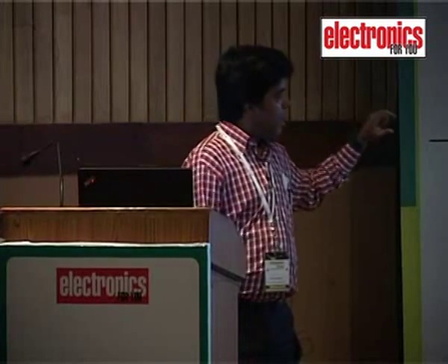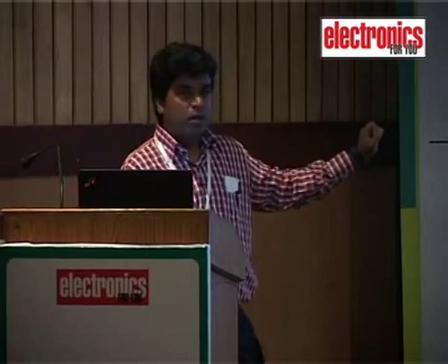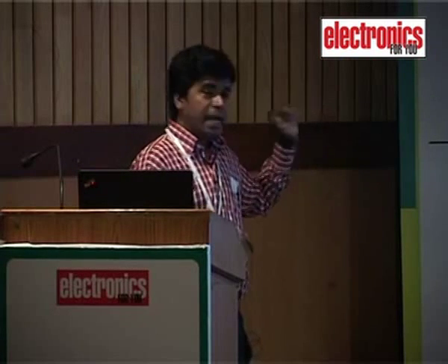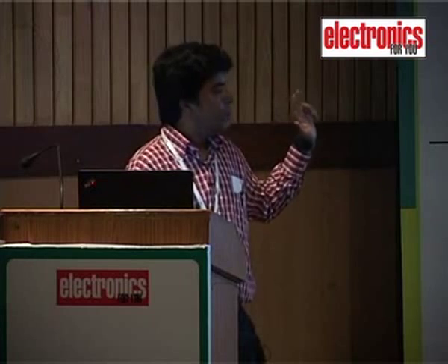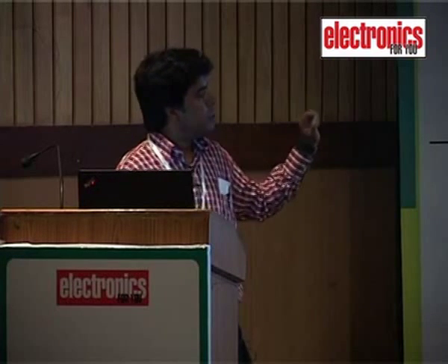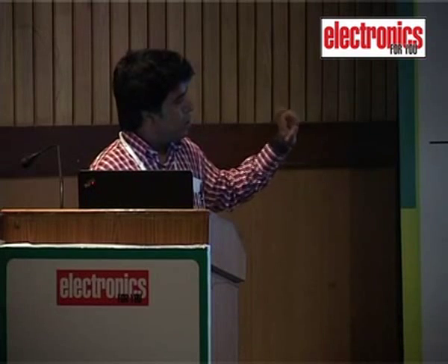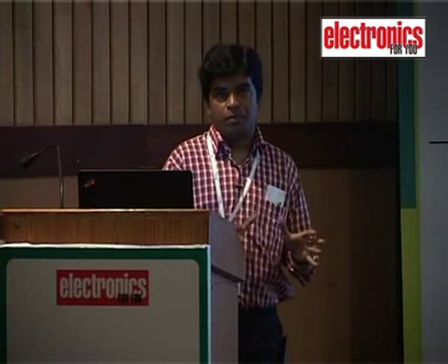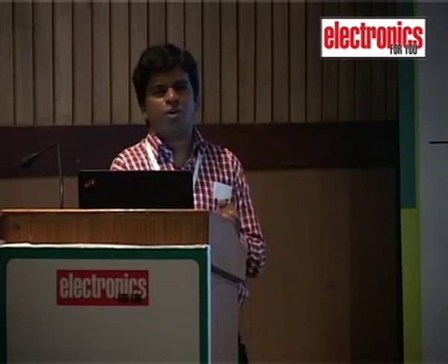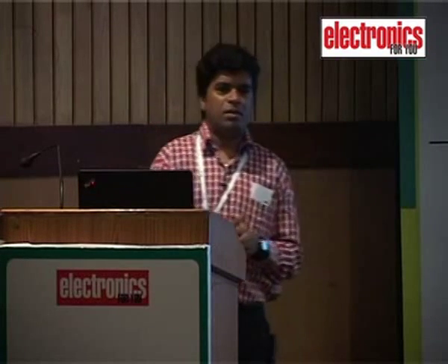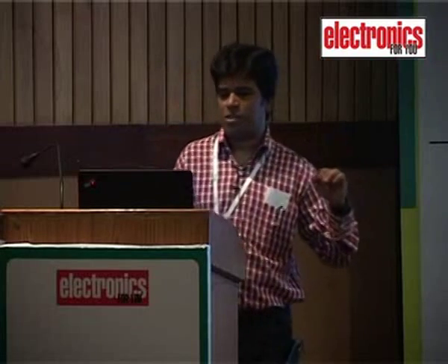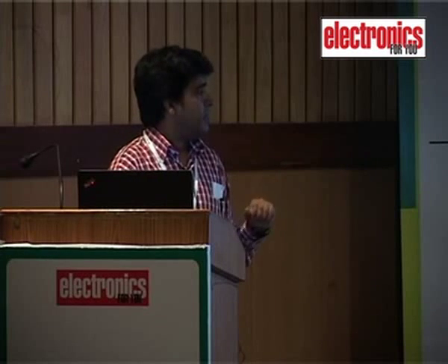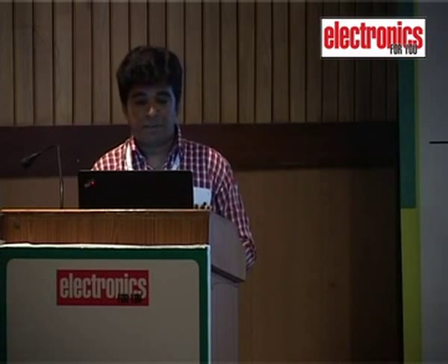Similarly for green, and for blue we are ORing 3 pixels out of the available 8 of blue. So what we have essentially is B0 and B1, G0 and G1, and R0 and R1. These are redundant bits which we can ignore. Their intensity is going to be very low, so even if we ignore them, it is not going to make much difference in the final pixel. This is one level where we have good compression. The unused bits are redundant, and that's how in 8 bits we accommodate 256 levels.